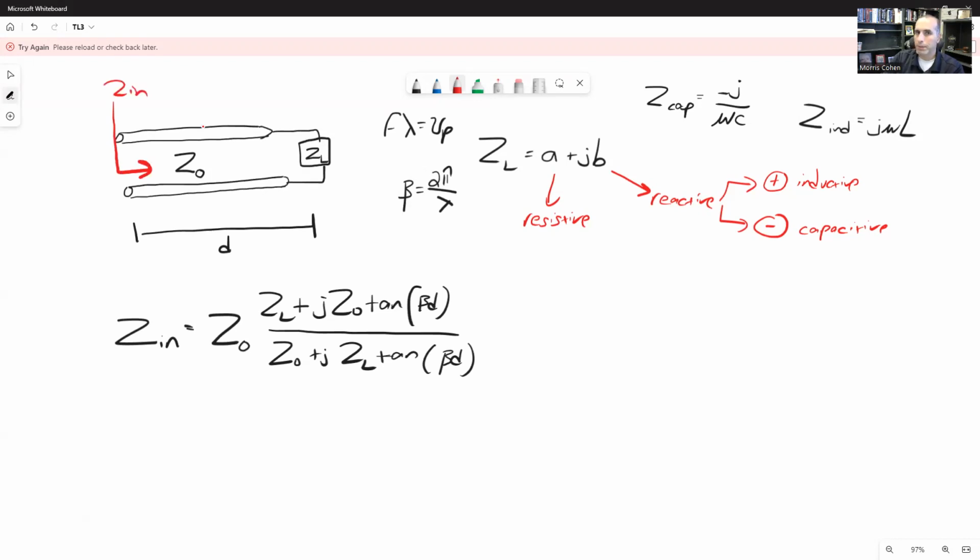Right, so what input impedance means, just to remind you, is that if you just had a wall that had 2 terminals in it, and you had no idea what was on the other side of the wall, but you had the ability to place a voltmeter between those 2 terminals and then measure the current that appears. And if you convert each of the voltage and the current into phasors, and you take the ratio of the voltage to the current, that ratio will be equal to Zin.